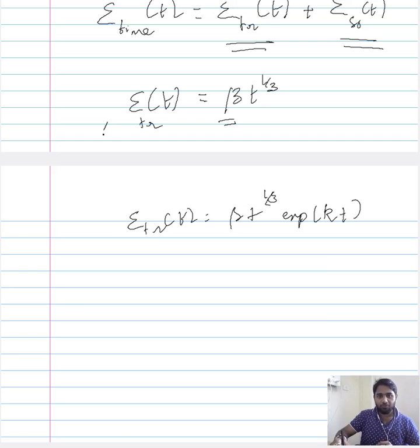The reason for this extension is that in the subsequent eras, the instantaneous creep and the transient creep were categorized into stage 1, as we have seen earlier. The instantaneous creep has this format wherein the strain increases exponentially, and the transient creep is of this format wherein you have a decelerating slope that is characterized by this particular relation.